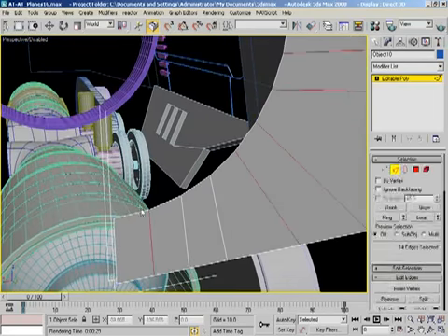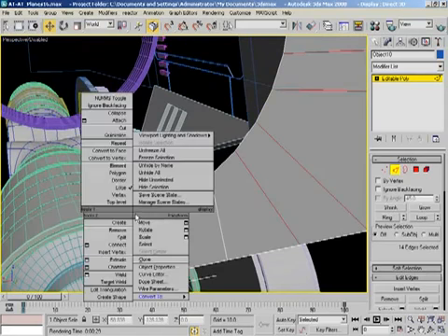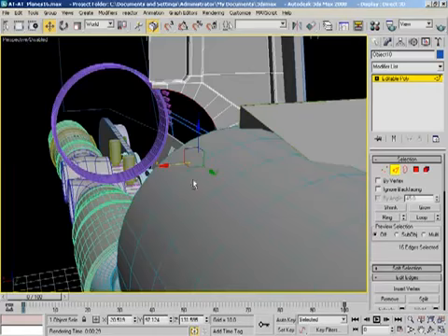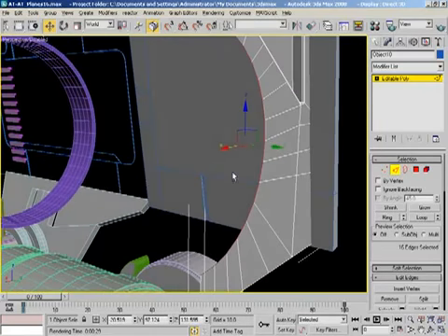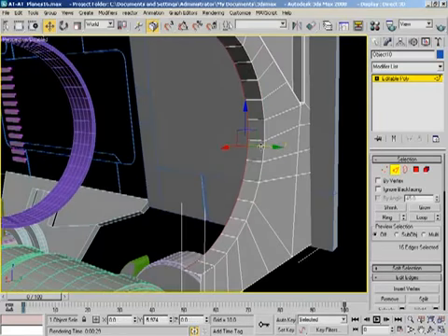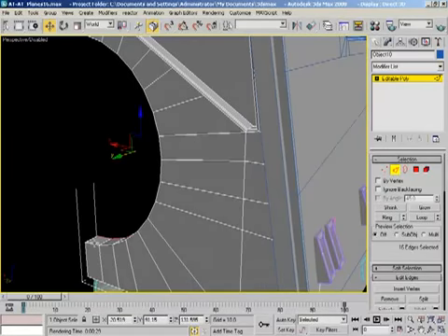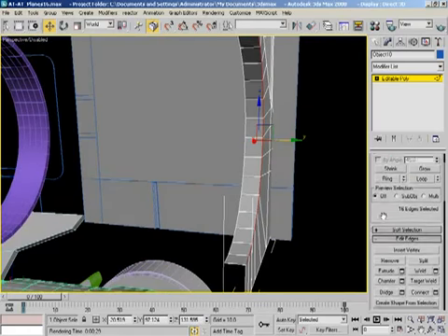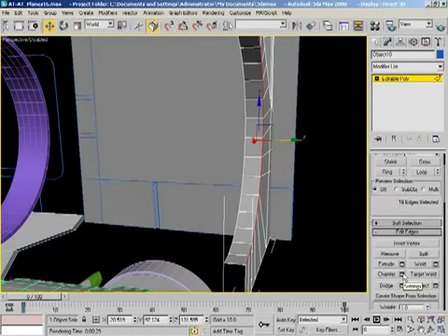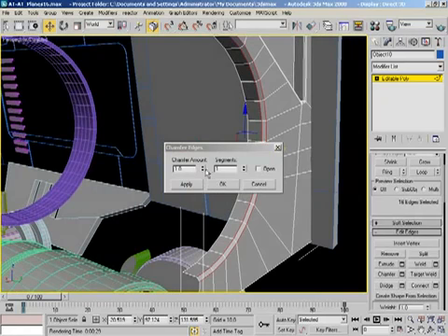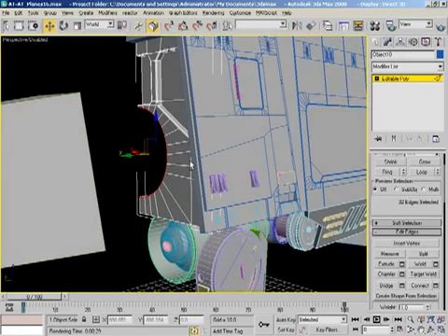So now we switch back over to edges. Let's grab this edge. And if I hit loop, now I get the actual loop, which is pretty amazing. And we'll just shift drag a copy of that out a little bit, and that should add some nice thickness. Now if we come back over here and we loop again, we should now be able to chamfer these guys and create a nice little beveled surface there. Okie dokie. And that's pretty special.